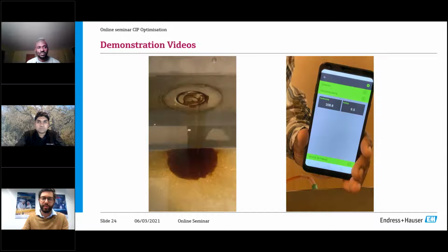What is the minimum resolution for the QMW43? Well, in terms of the build-up heights, basically it starts reading from 0.1, which is a slight tweak, because if it is displaying 0.1, it means that the build-up on the sensor surface is actually 0.1 or below. It doesn't actually show values below 0.1.